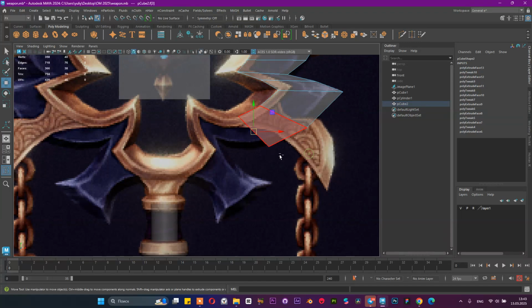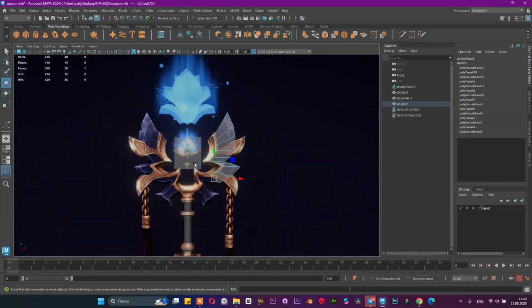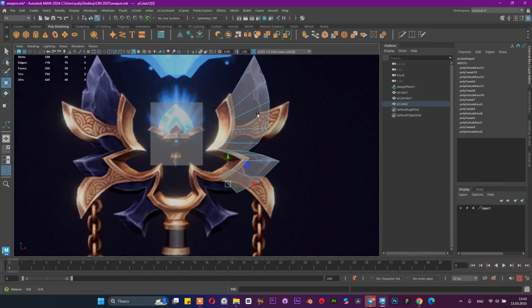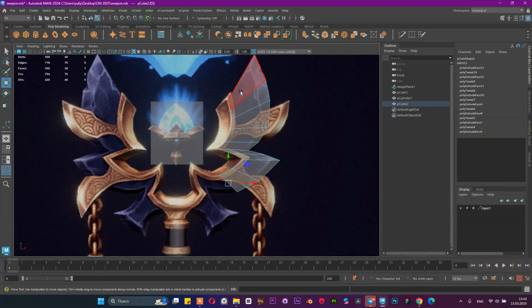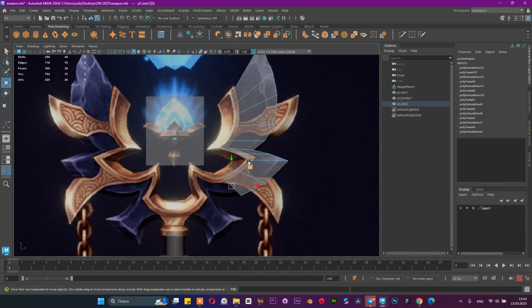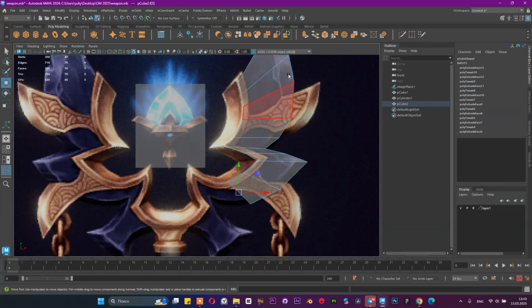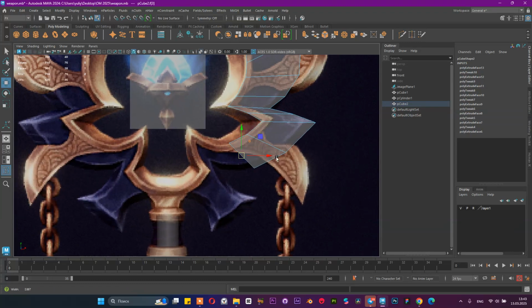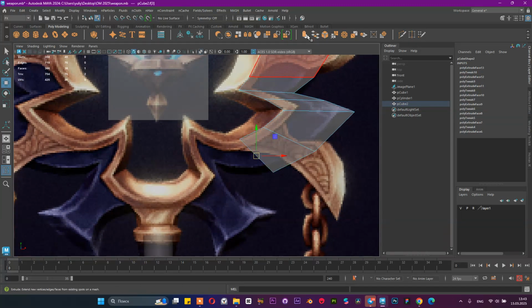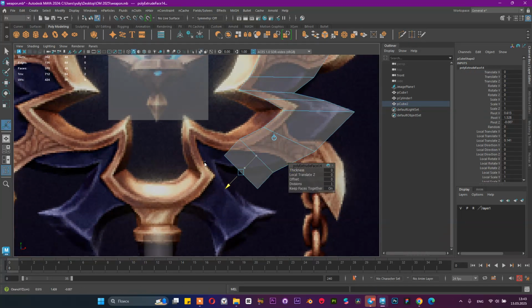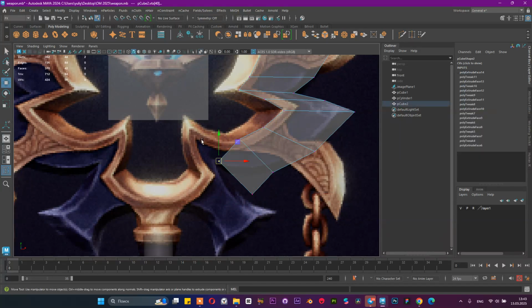First, it shouldn't be really detailed. If you put edges really close, it's difficult to manipulate. Make enough to provide the basic shape. After that, we can make some bevels, or we can add some more multicuts in between if it's necessary. But try to keep it as low as you can.